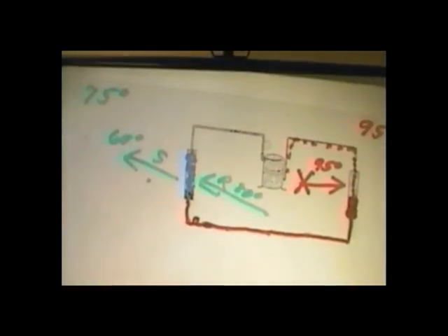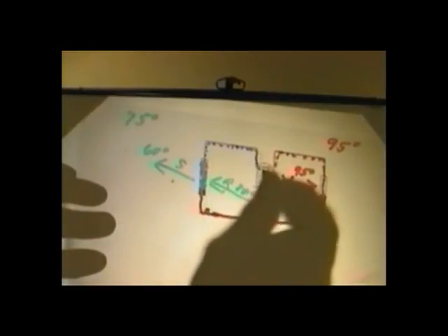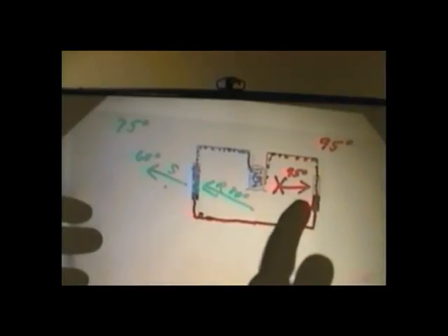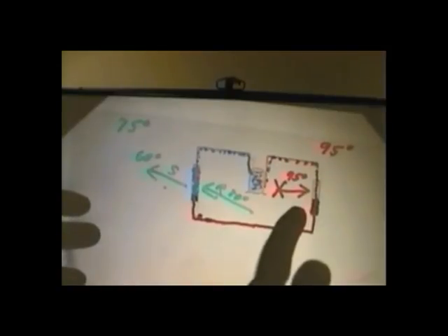Now, at the end of the evaporator, of course, everything is working ideally. We now have vapor refrigerant going down the suction line and into the dome of the compressor, because the compressors are low-side domes. Again, a perfectly operating system. But let's talk a little bit more about this. For example, we're going to say that this is, in fact, a perfectly charged system, and only for the example, we're going to say that it is a 30 over ambient condenser.